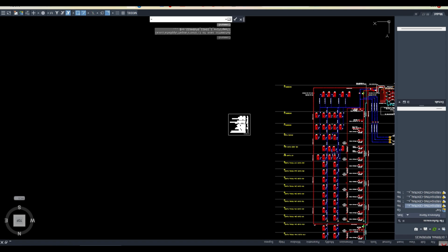So I'm telling you 90 meters till the parapet, so obviously the roof floor level itself will be less than 90, because the parapet is always not less than 1.2 meters, right? So in any case, it will always be less than 90 meters, because the height from the grade level till the parapet is 90 meters. It means till the roof level, the distance is obviously less than 90 meters. So it comes in high rise building, not in super high rise. Correct? So that's how you count it.